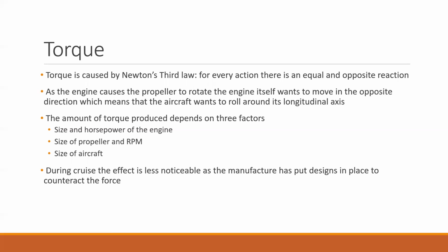And so torque can be affected in a few different ways. It depends on the size and the horsepower of the engine. Obviously the more horses you have coming out of that engine, the more torque it's going to have. And then propeller size: if you have a really big propeller, it's going to affect it a lot more. And then the overall size of the aircraft, which will help in resisting this torque force.